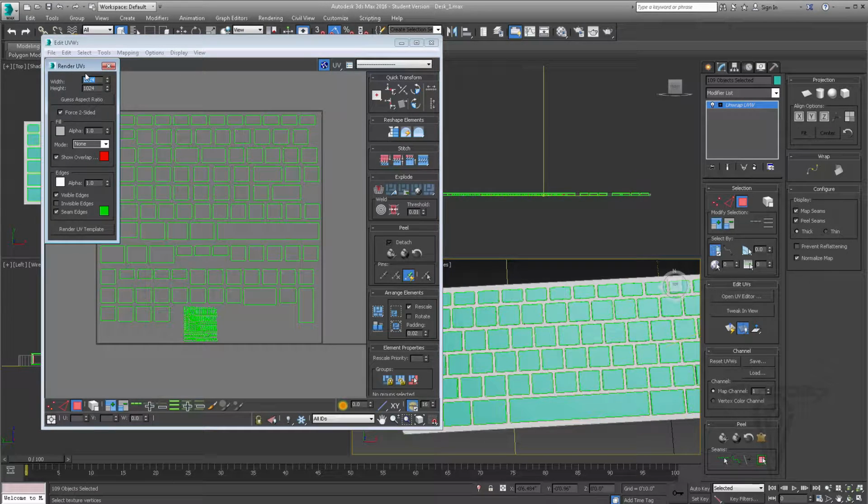And so my suggestion is to bring it up double, 2048 by 2048. Now you need to make sure you keep this square. Even though you can see that we did keep it square in the design, it's also a good idea because when it comes to 3D programs and rendering, they like even numbers that are square for your texture files. It's easier for it to compute the data. And if you really wanted high-res texture, you can go 4096 by 4096, and that's a 4K file.